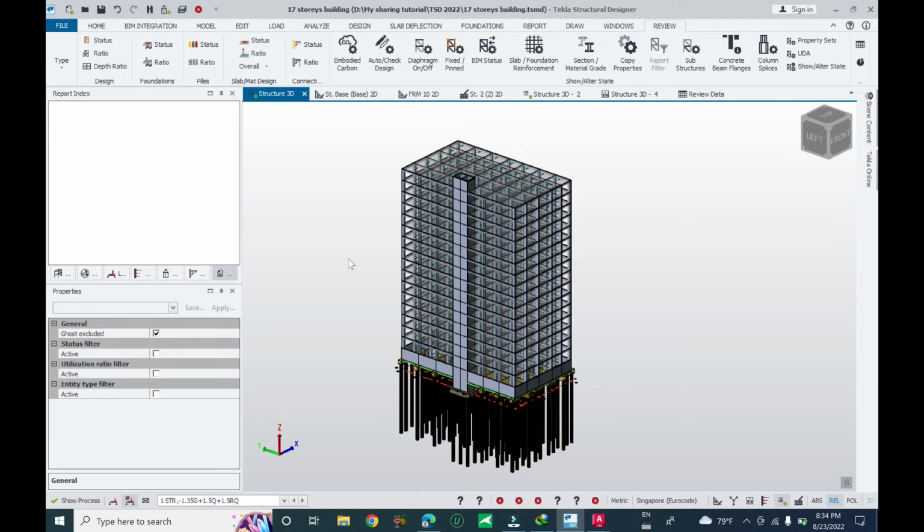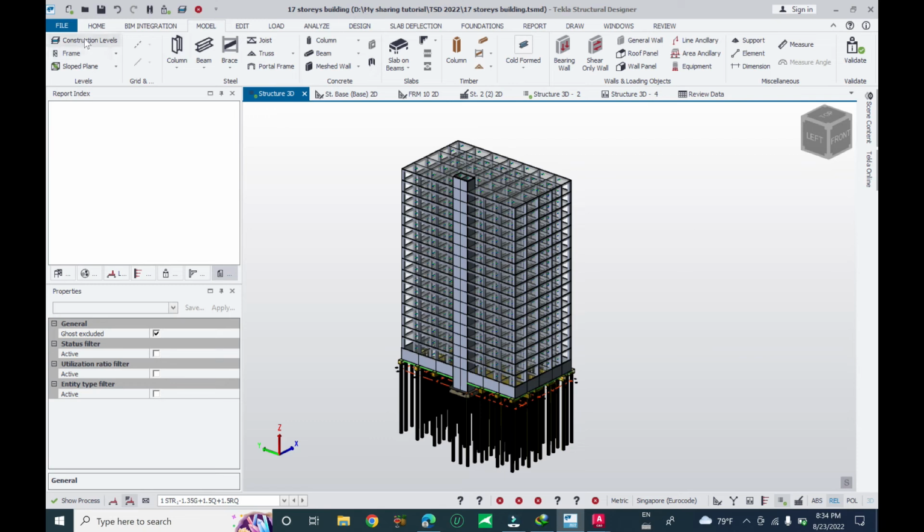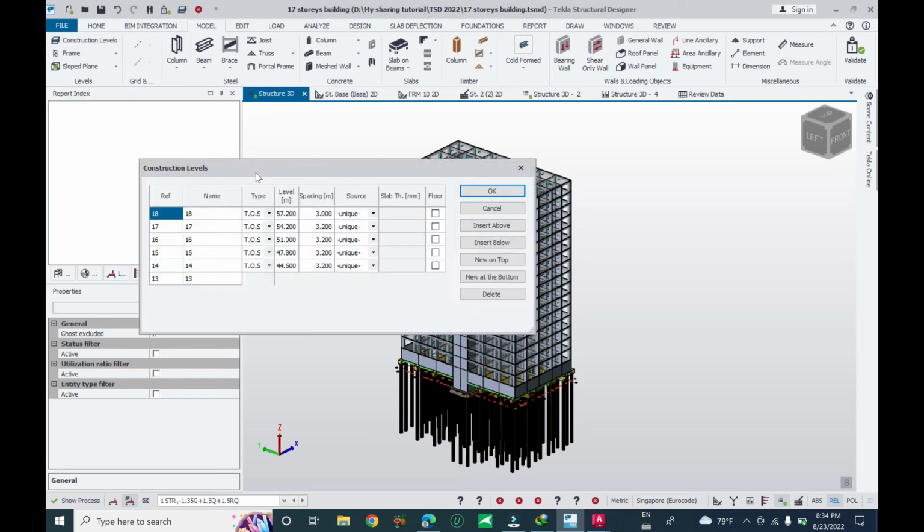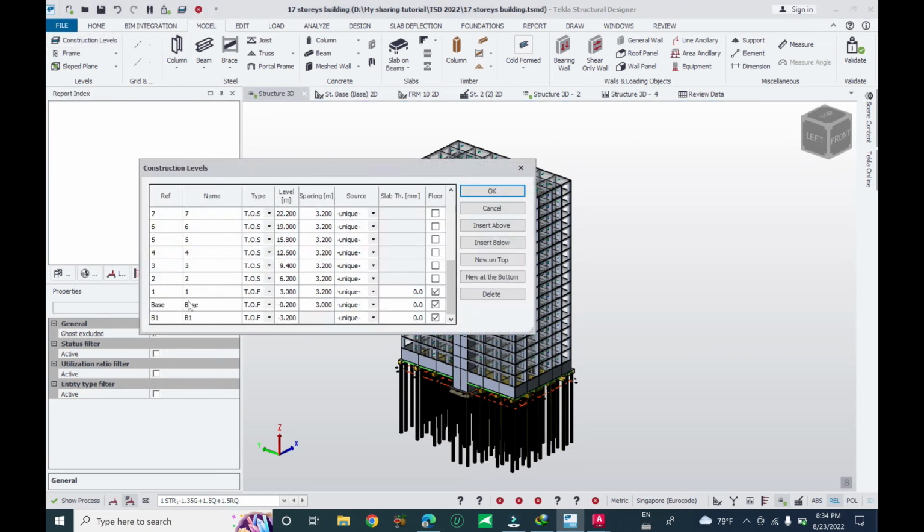Okay, you can use modeling starting from construction lines, do everything from here by using add beam and using the master story with similar story, other story. Okay, I want to use the 16 story similar with 18 story. When you model one story, the other story will be the same, or you can keep it unique.